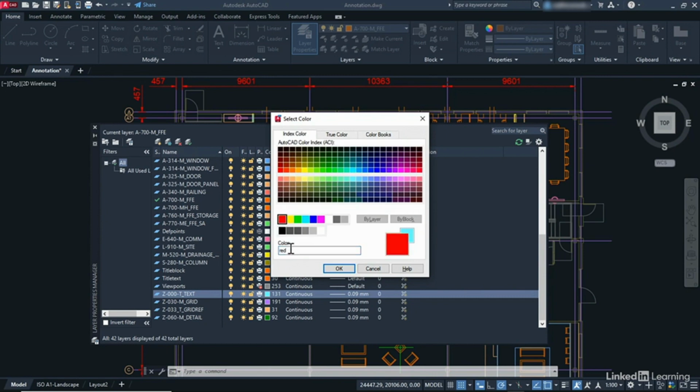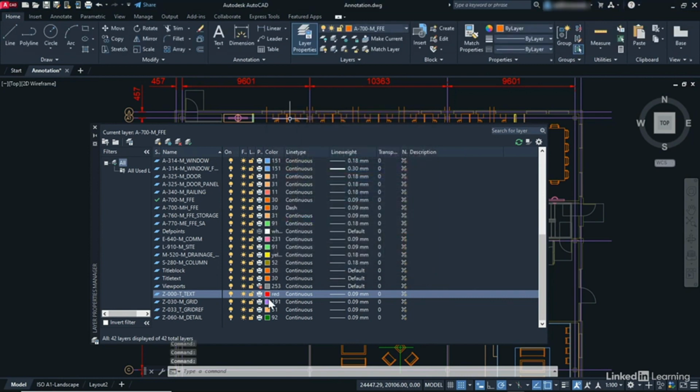When you click on it, it will say red. It's one of the old original AutoCAD colors, way back when we used to use pen plotters and things. But the idea is I want you to use red, that color right there. So that little box there, Index Color 1. I could just type in 1 as the number of the color and click on OK, and that will still say red in the Layer Properties Manager.